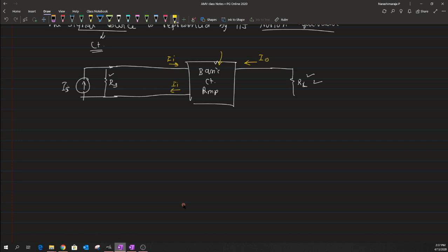Okay, so with that being said, this is how the structure is, and we also have this feedback network being applied, and this feedback network has to sample a current. Just because the basic amplifier spits out a current, we want to sample that particular current. Now the way that one could think about the sampling of a current is by thinking about a current meter.